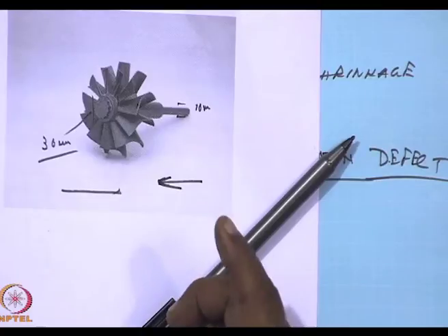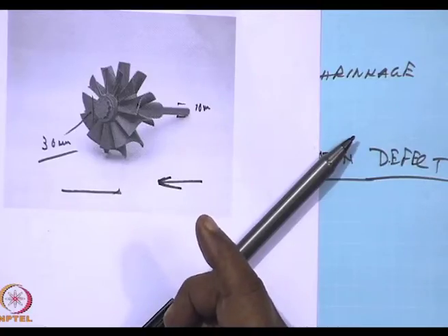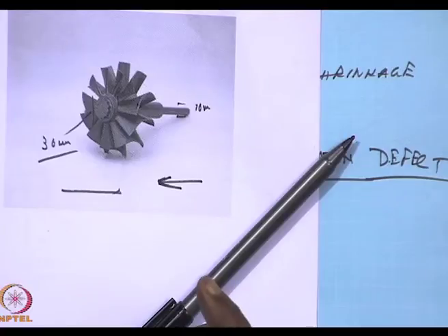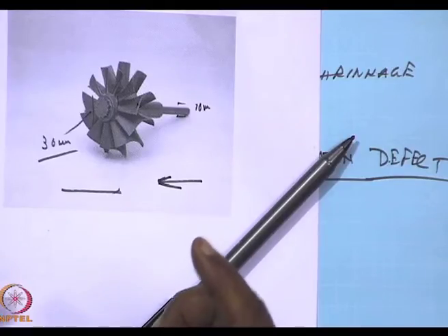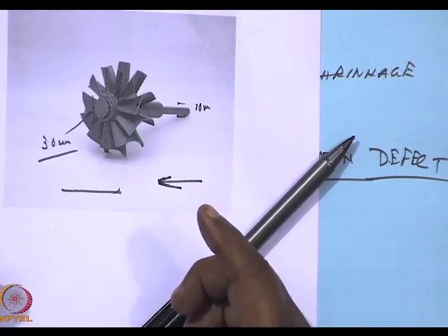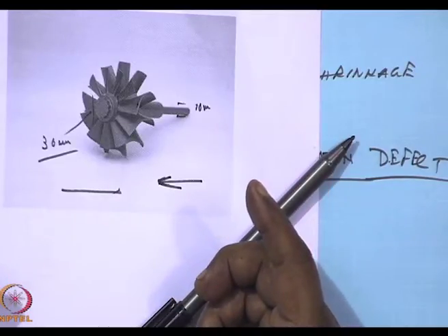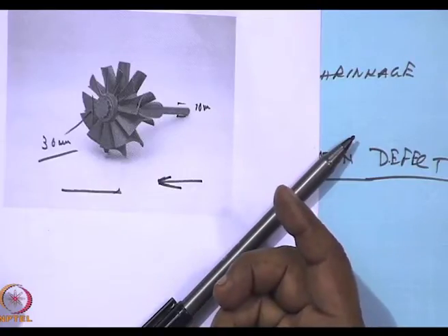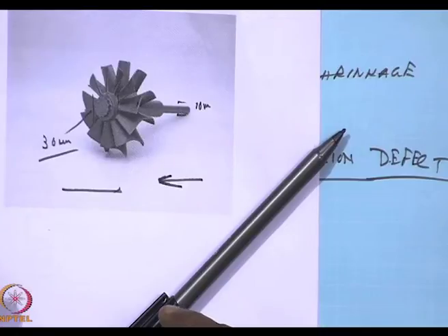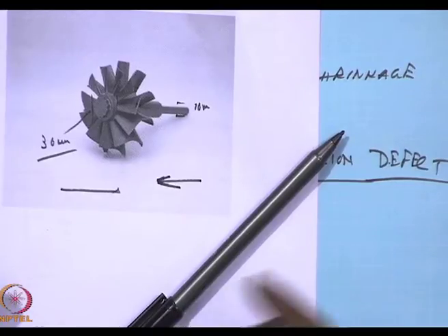In this complex geometry, having a defect-free casting requires tremendous control on the viscosity of the liquid. The injection pressure, the force at which you are injecting the liquid, the hold time, the time you are holding the material in the mold, temperature, which controls viscosity.